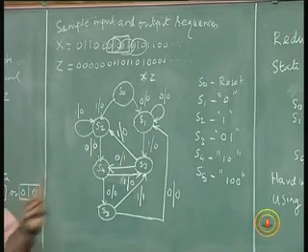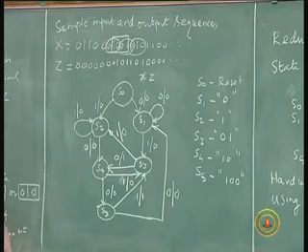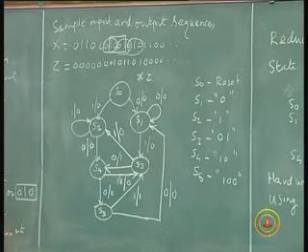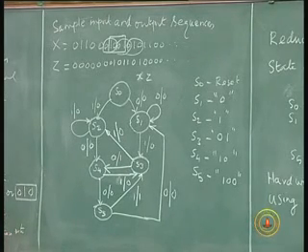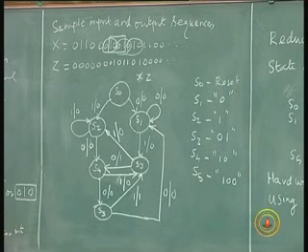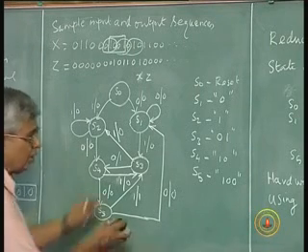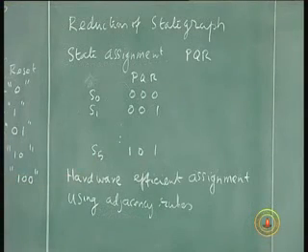We will do one more example of the state graph generation, this time using a Moore machine. We have not used that so far. We have done only Mealy. So let us do a Moore machine state graph. The rest of the thing is easy. Once we have a state graph, you know state assignment. I am not going to talk about all these things one more time. We will have a state graph, then from there you know the reduction if necessary.